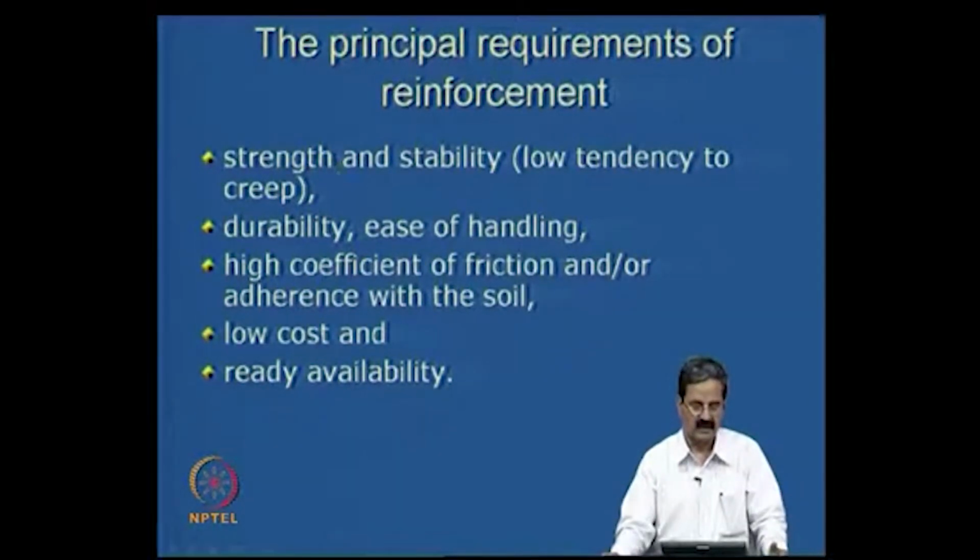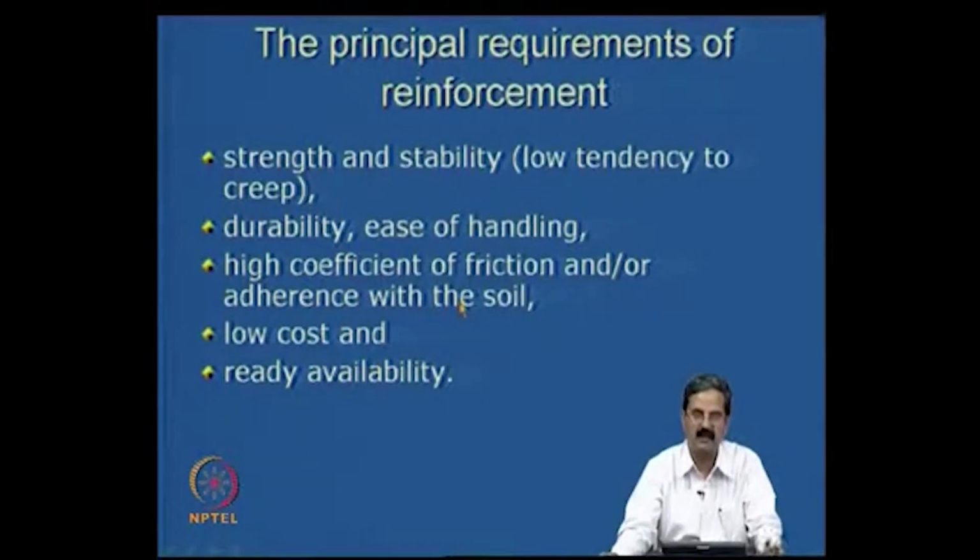Very importantly, a high coefficient of friction or adherence with the soil, like we need good friction between the soil and reinforcement. That's very important, because that's the whole concept of reinforced soil. Now, it should have low cost also. Apart from technical advantages, like we said that we can increase the width of the reinforced concrete, the thickness of the stem and all that in the case of reinforced concrete retaining walls, we essentially want low cost and ready availability.